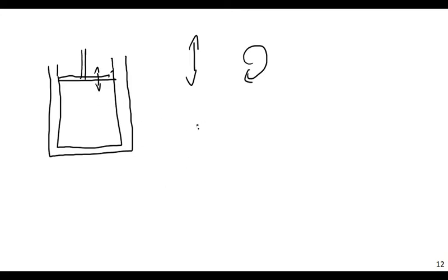You can, for example, use gearing on it once it's rotating. You can change the torque in it. You can change velocity. You can transform between torque and rotational velocity just using gearing, right? If I have a rotating shaft, I can try to draw a gear. If I want to make it rotate slower, I can just attach it to a larger gear, right? And for every one rotation of the smaller gear, the larger one will do only half a rotation or a third of a rotation or whatever.